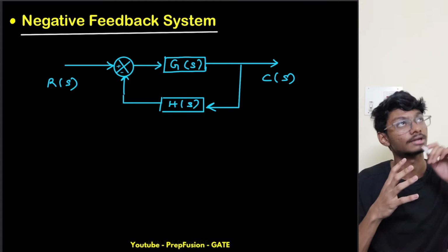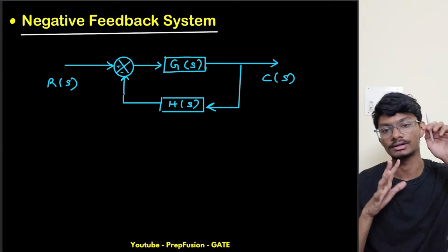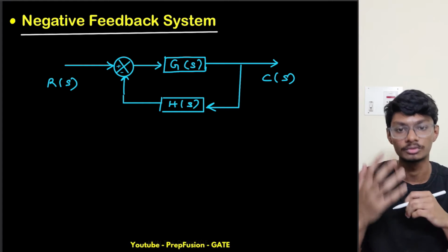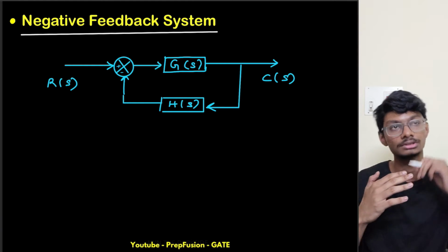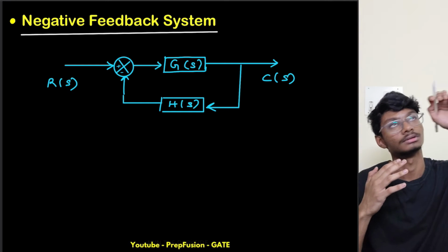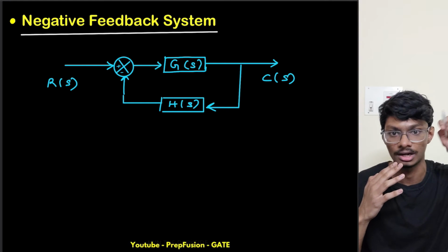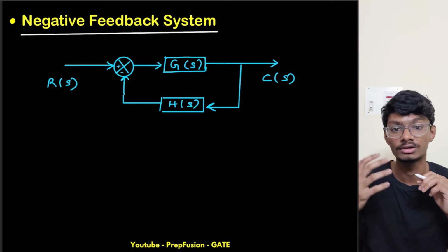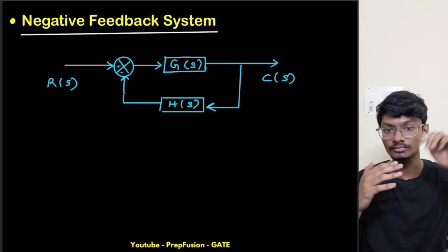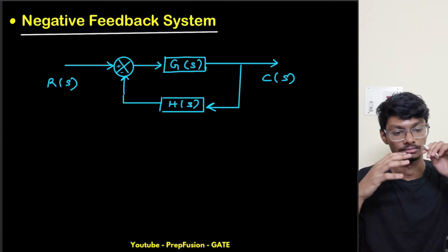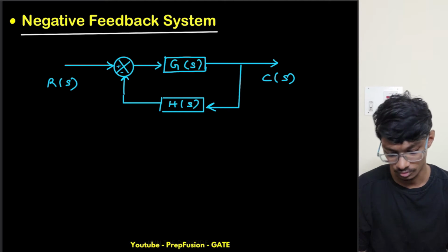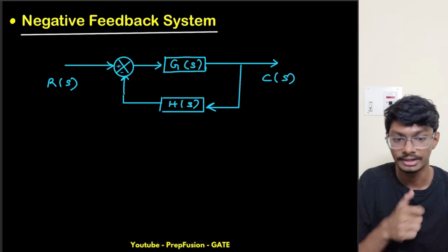If the fan tries to destabilize, if the wind speed decreases or increases, it will do the opposite effect. If the wind speed decreases, the system will try to increase the power so that the wind speed goes back to our level. And if the wind speed increases, the system will decrease the power so that the wind speed gets back to the desired level. This is what negative feedback does.